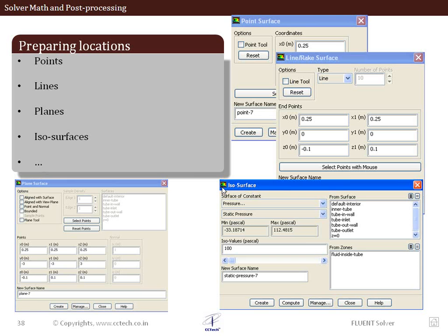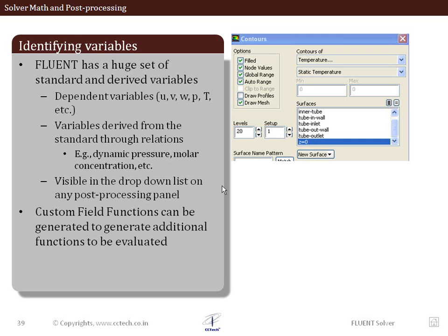This is very helpful if you want to analyze heat transfer and ventilation, air conditioning kind of analysis to be done for HVAC studies. People generate such velocity isosurfaces, and then they analyze the temperature contours on such surfaces. It's very helpful to have an overview of the different temperature distribution inside the room or inside a domain at specific velocity surfaces.